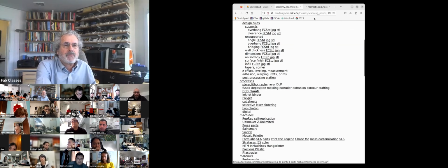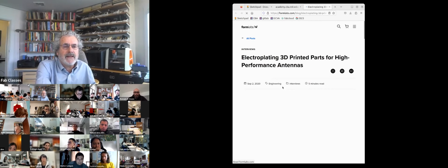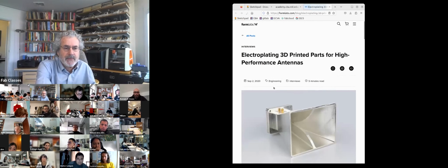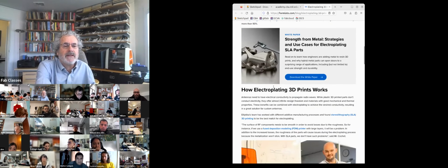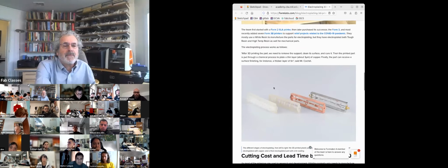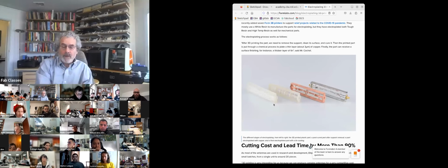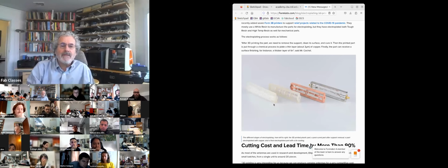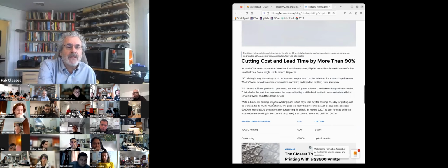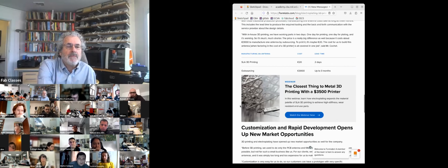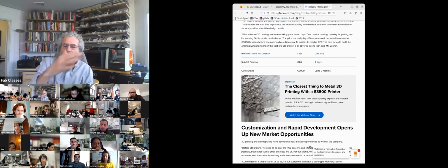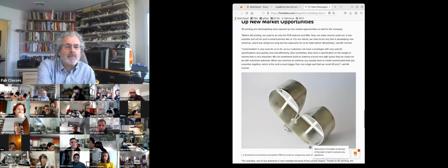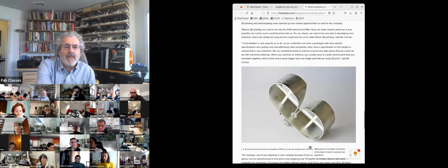And then a really powerful technique is plating. In particular, you can electroplate, which is where you print in a polymer, you can coat it and then put it in a bath where you drive a conductor on it. So rather than printing a solid metal part, you can make what look like metal parts and have conducting surfaces by electroplating. And this isn't that difficult to do. The chemistry is not very bad for electroplating.